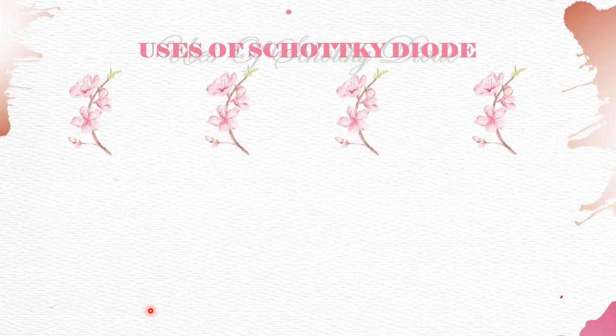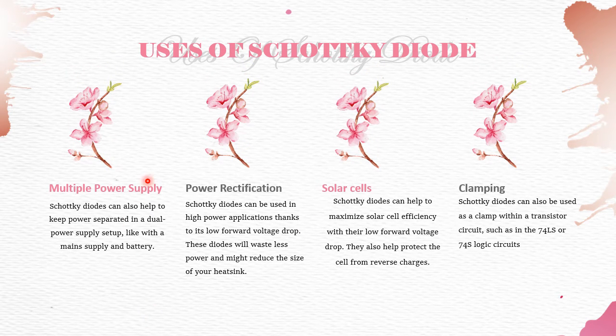We list out the four uses of Schottky diode. First, multiple power supply. Schottky diode can also help to keep power separated in dual power supply setup like with a main supply and battery. Second, power rectification. Schottky diode can be used in high power application thanks to its low forward voltage drop. This diode will waste less power and might reduce the size of your heatsink.